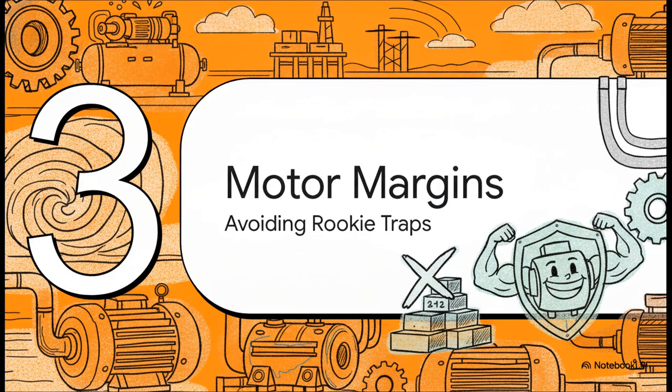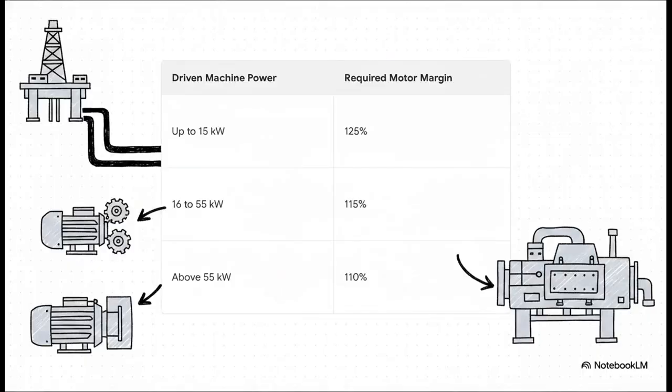Which brings us to Section 3, adding crucial motor margins. We really want to avoid the classic rookie trap here. Here is a massive rookie mistake, simply looking at the raw mechanical power required by the driven machines and dropping those nameplate ratings straight into your load schedule. You can't do that. You have to apply industry rules of thumb. The motor rating absolutely must exceed the machine's base requirement by a specific margin.